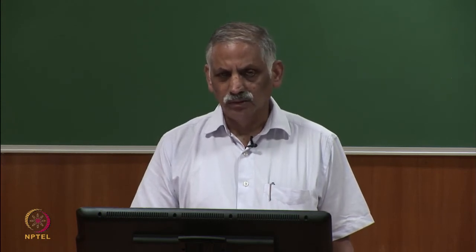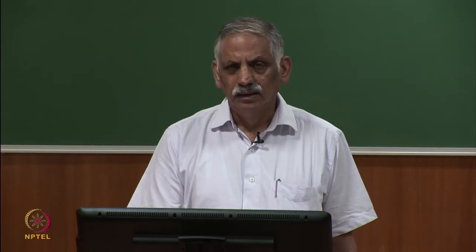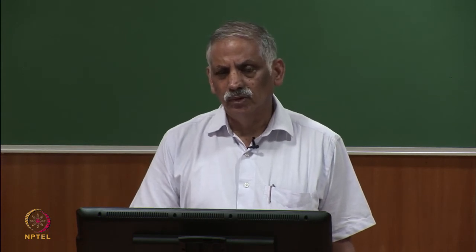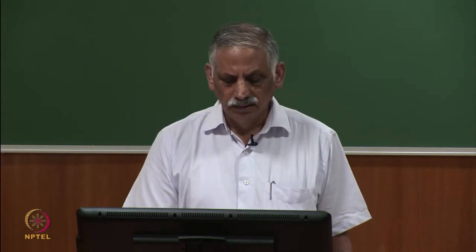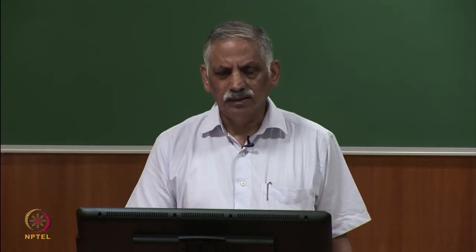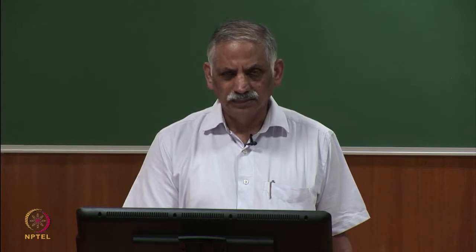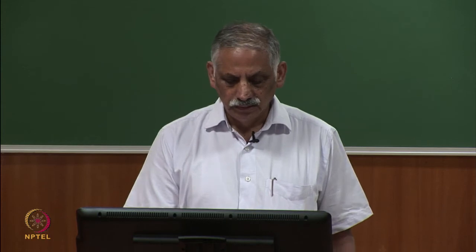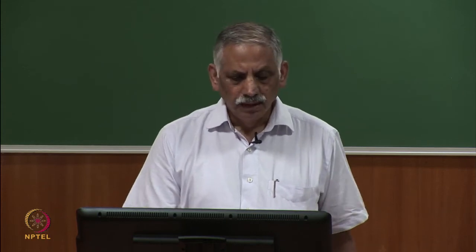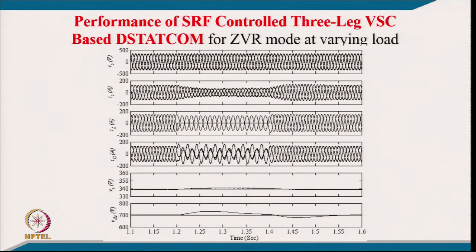Earlier we were modeling not through MATLAB, we were just making our own program code and then simulating the performance. But now such software like MATLAB are available, so you can develop the total model itself from blocks for this complete system including the control algorithm, and then we are able to get the performance of this D STATCOM. So, this is a typical case study, the performance of a synchronous reference frame control 3 leg voltage source converter based D STATCOM for zero voltage regulation mode at varying load.